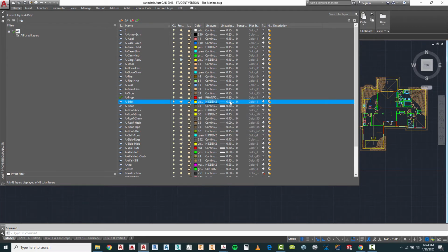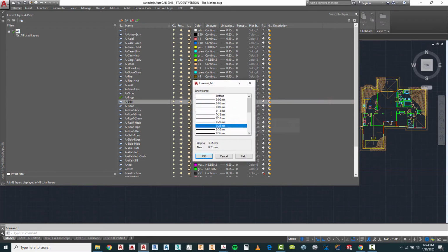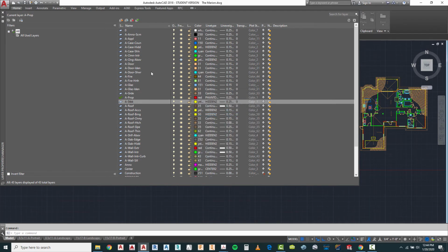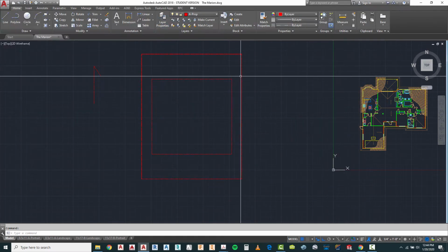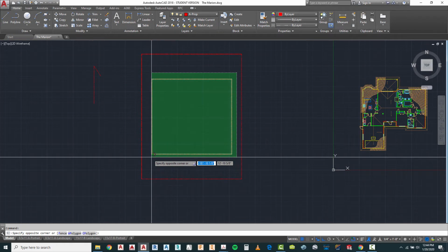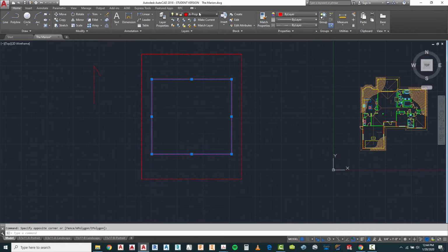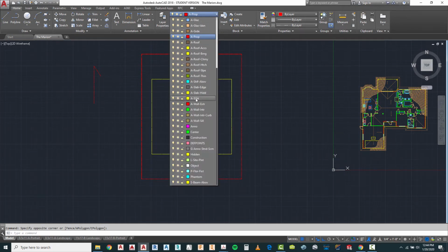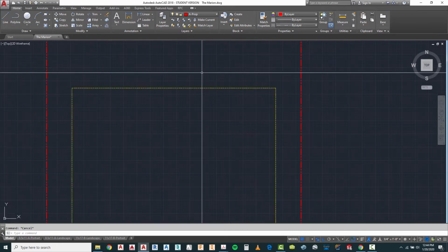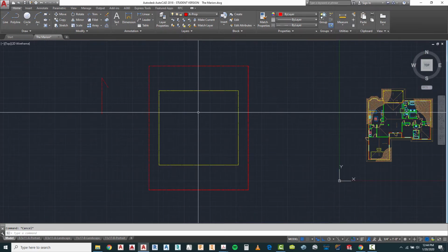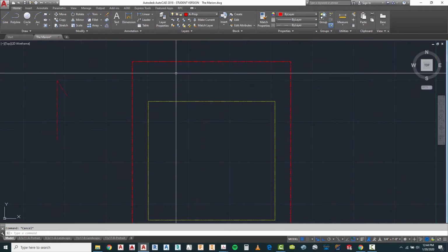And the line weight I am going to want for that is going to be 0.15. So I'm going to close that up, and I'm going to turn on those. I'm going to select those layers and go to A-setback for that. Then I can zoom in, and I'm taking a look at my piece of property here.